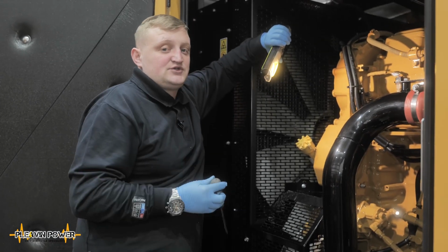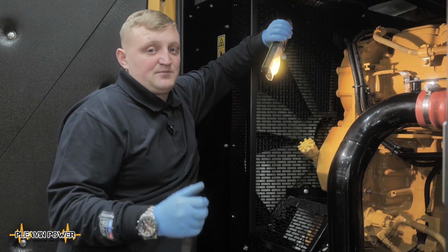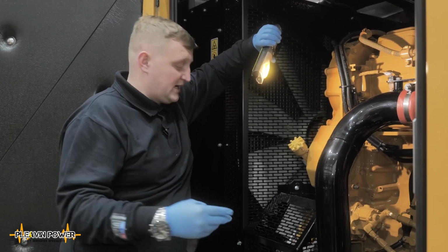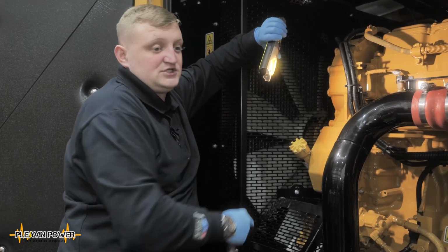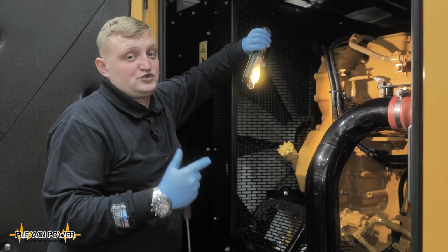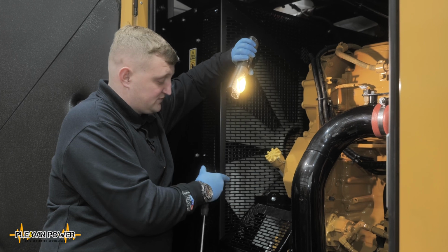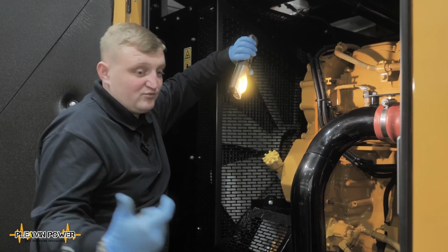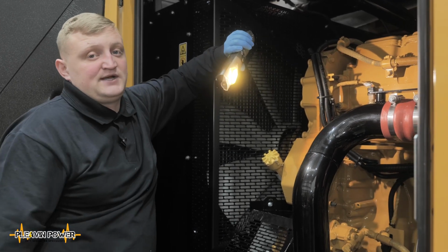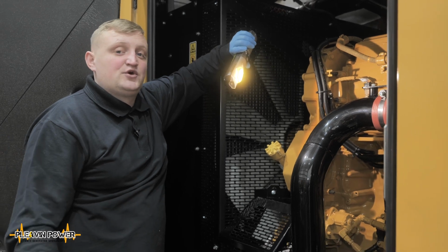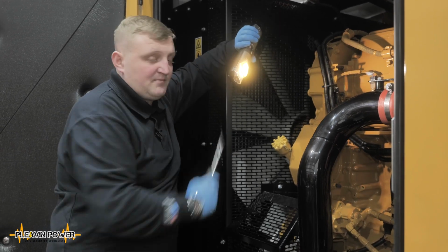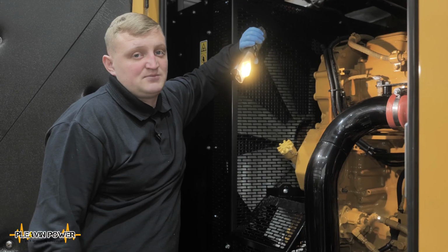It's a little bit like the tyres on your car. If they're left for a long period of time, they can become cracked and worn and deteriorate over time. Belts with cracks and deterioration marks or stress marks can fail under stress or under load, and in this case where they operate under extreme tension, they can snap, jam the fan, and in the worst case scenario cause the fan to explode and burst the radiator. So it's extremely important to ensure that the charge alternator belt and the fan belt are changed every 2 to 3 years as a minimum.